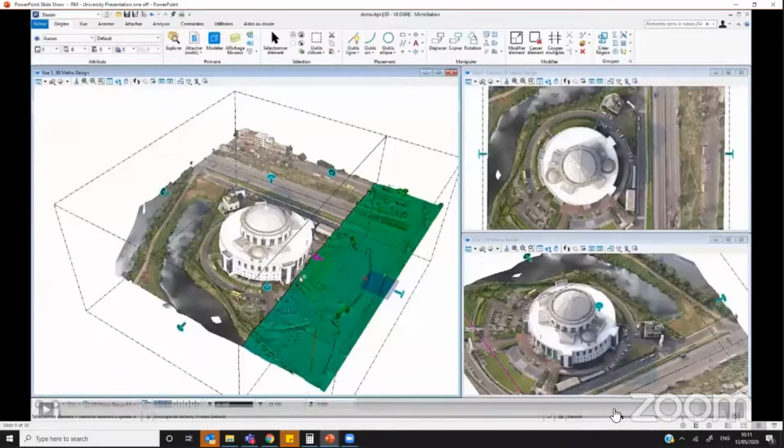So what you saw there was 3 main steps: capturing your images, loading in, aerial triangulation, and reconstruction. Around 90% of that work is all automated, and maybe only 10% is manual input, very small manual input. The rest is just the computer processing to create the reality meshes. So in that sense, not much work on your side at all, and you can get some really nice, highly visual reality meshes out the other end.